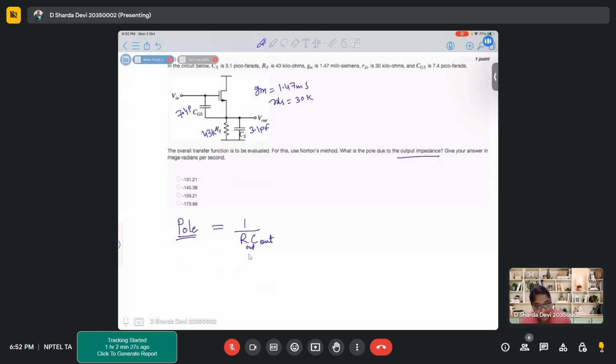So now first of all, Z out. This is the drain node, this is source, gate. So in this particular circuit, what is the R out or Z out that we will observe? It will be 1 upon Gm parallel RS parallel RDS.